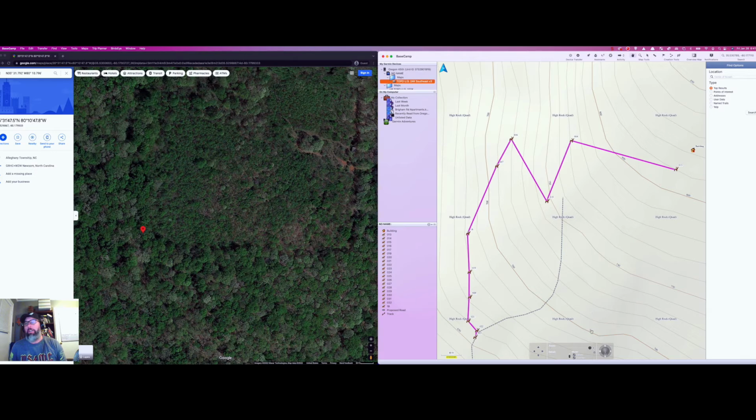So you're at 700 feet right here, and then you've got 710, 720, 730, 740, 750. So each one of those represents 10 feet in elevation gain as you're going from left to right. So 700, 710. I knew from this is 690, almost 680. So we're probably at 685, maybe, let's say. Not even quite that, 683.